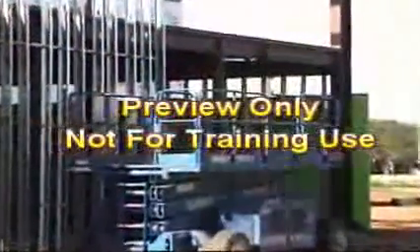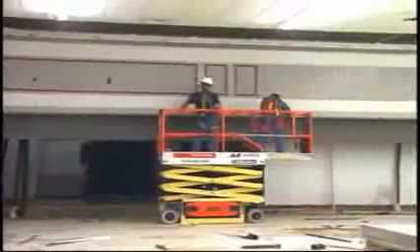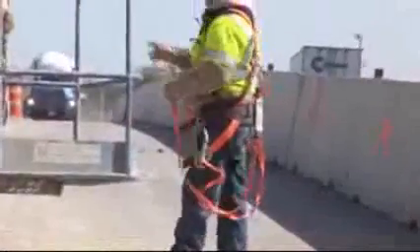Guardrails that are properly designed, maintained, and meet OSHA guardrail requirements are sufficient fall protection. If the guardrail does not meet OSHA standards, or if an employee leaves the safety of the work platform, then a personal fall arrest system utilizing a full body harness is required. All aerial lifts require fall protection.